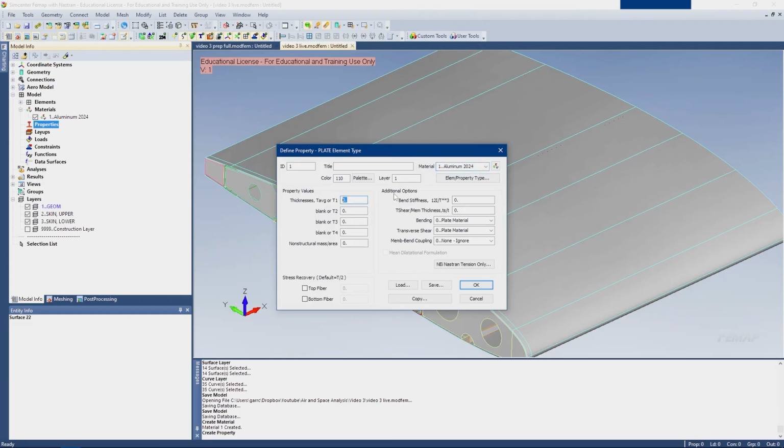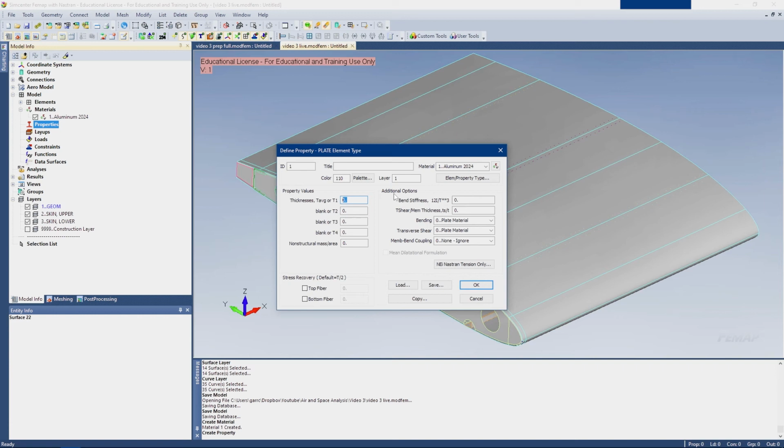And generally 2D elements are just as accurate as 3-dimensional elements, like the tetrahedron elements that you'd be seeing if you just hit mesh on a basic analysis program. But the main benefit is you can get the same accuracy with way fewer elements.